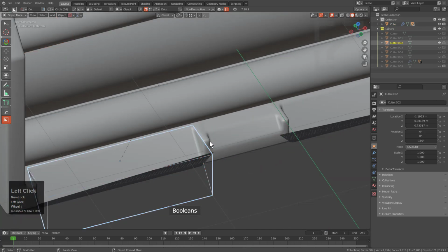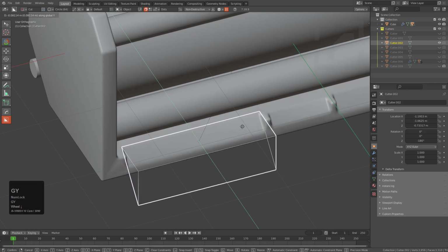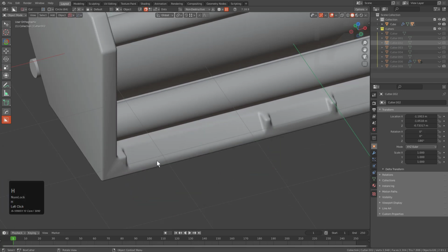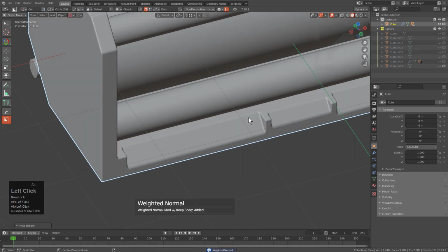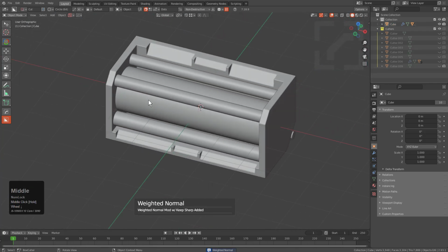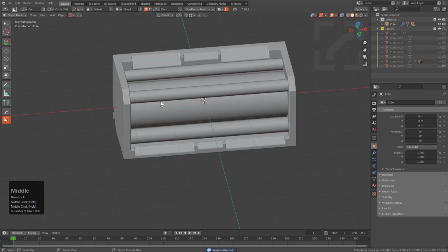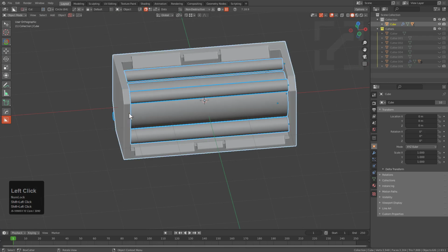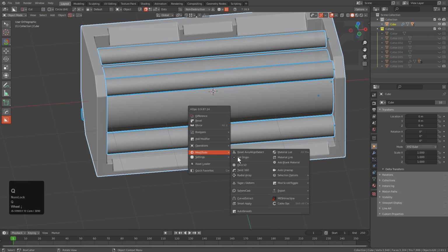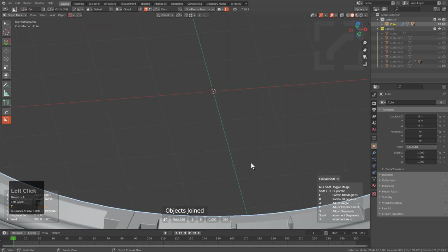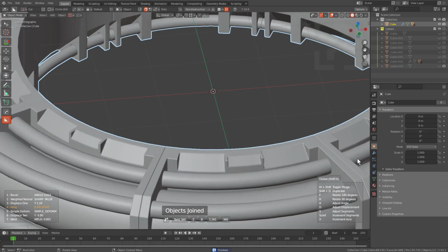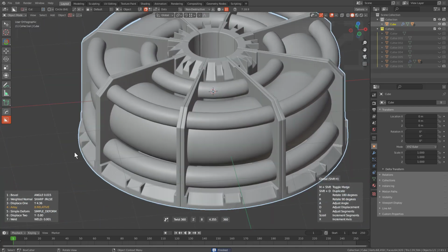So let's just bring back this particular wedge, and we just want to bring it out so that way it terminates a little bit earlier with the surface than we had it going before. And we could also put a weighted normal on this just because it'll make it look better. And that's really it. So we want this to be the main object because we want everything to be joined to this one that has the bevel. And so we go back under dice again, we press T, and we click and apply, and we're now inside of dice, inside of the twist operation after completing it.